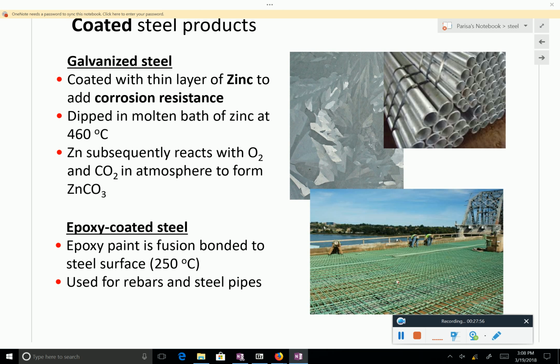So during the winter, when there is ice, what happens? They come and they put a lot of salt on the road, and the salt gets into concrete and it makes the steel corrode. So that's why you have to come up with all sorts of tricks to try to prevent corrosion from happening. It would be great if you could use stainless steel everywhere, but it's not economically feasible.